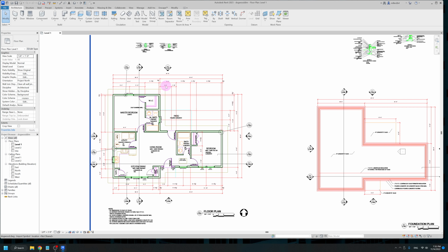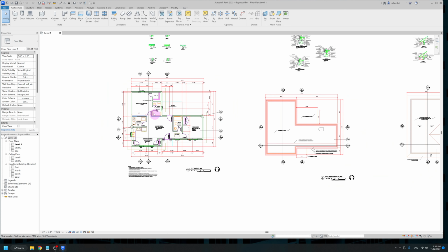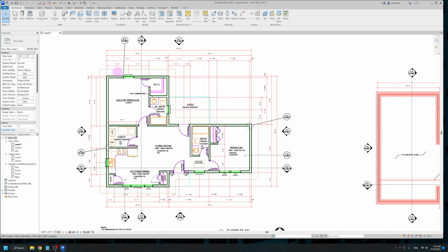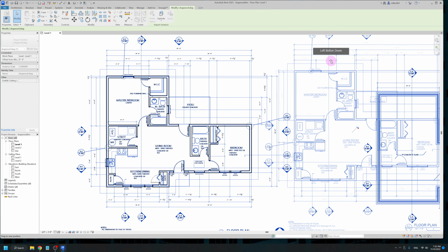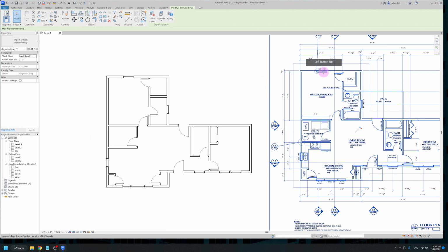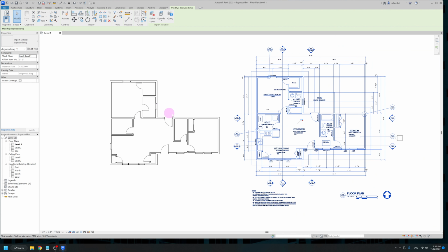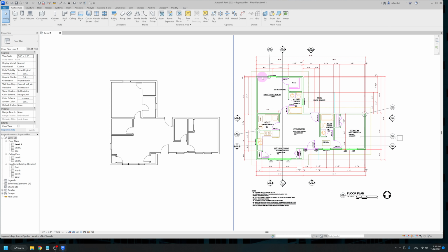One thing that I found really helpful, once I had every wall, door, window, and thing placed in my building, was to take the CAD plan in the background. I'm just clicking on the CAD plan and dragging it off to the side, so that as I place dimensions, I'm not going to mistakenly click on the plan itself to dimension to it.